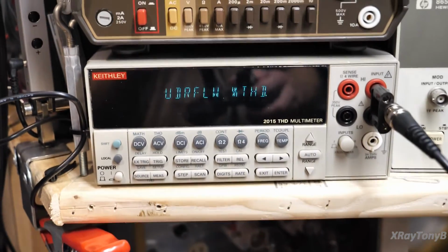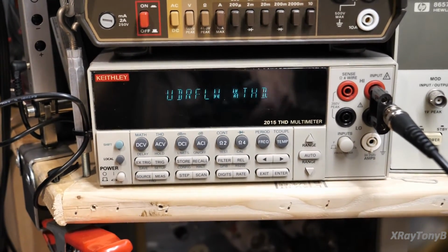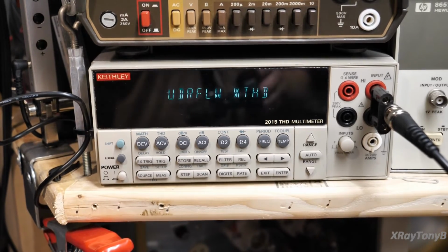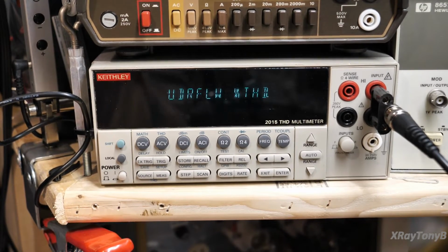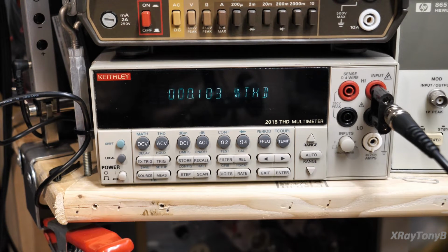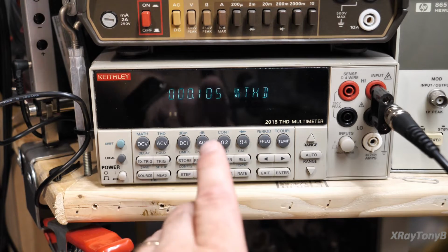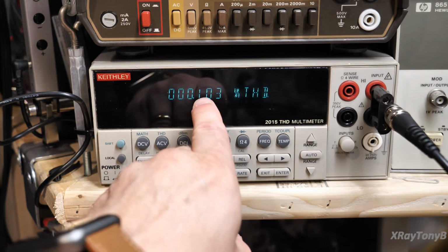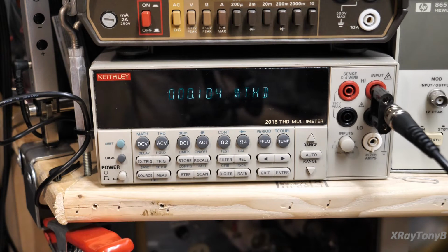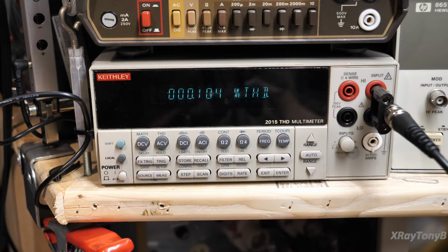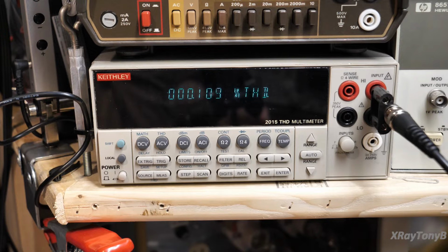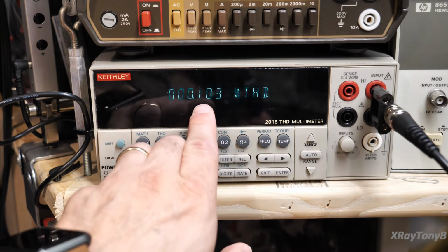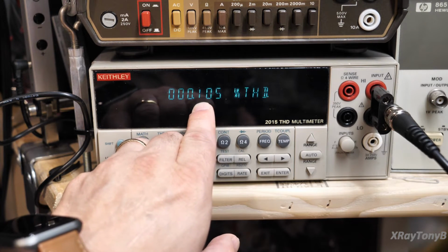So what we're going to do now is I've set the signal generator to such a level that I can get about 65 watts, 60 watts per channel. And we're going to see if the distortion between the two channels changes now. So if I turn this on, you can see the distortion is still pretty respectable. And this thing's running, like I said, at about 64 watts per channel. And it's still at 0.1. That's still a little bit high, but it's better than the other channel was.